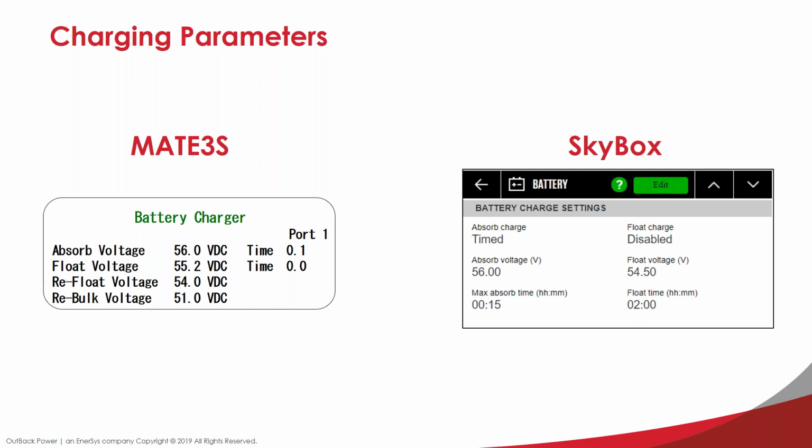And again, absorb voltage 56, pull that straight from the spec sheet, and the maximum absorb time, I have 15 minutes here, which is a little higher, but that's based on what I've seen, and this is a test setup.